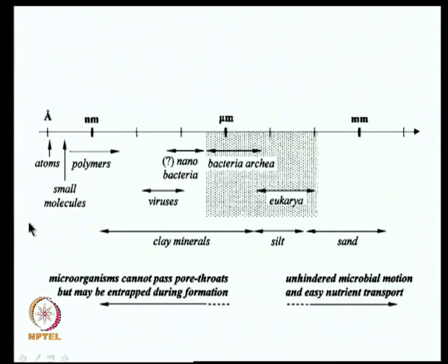But when you are trying to use it with soil, you should understand the grain size distribution and the particle size in soils. So definitely the clay minerals, say for example less than 75 microns, we can call them clays, and you have silt and sand materials. So there is some sort of relationship. The size of the bacteria is somewhat compatible with the sizes that you have, and one can really look at this as a means of understanding the interaction between clay minerals and the bacteria.